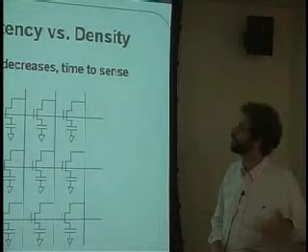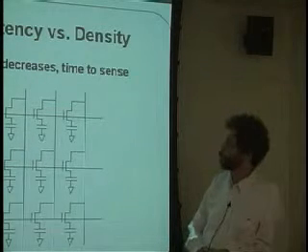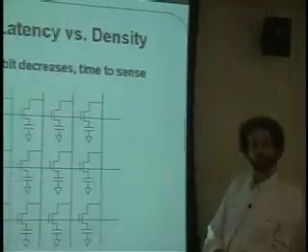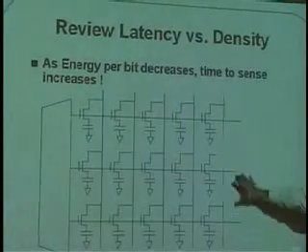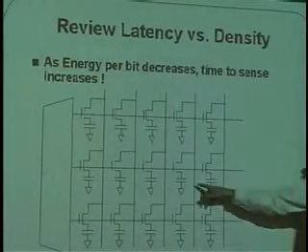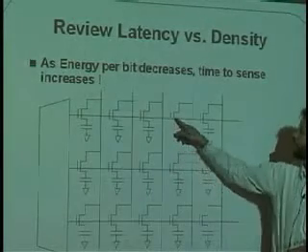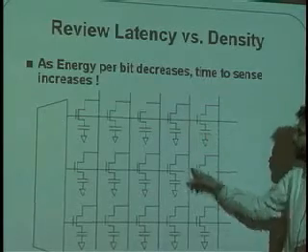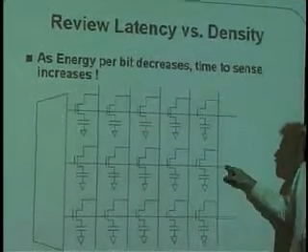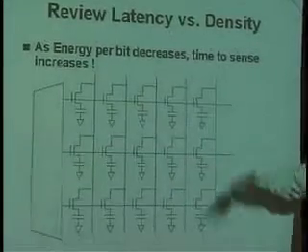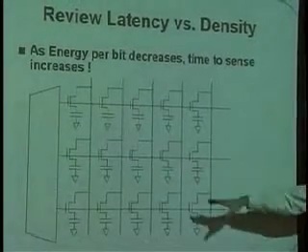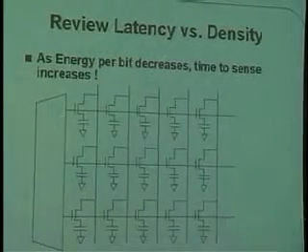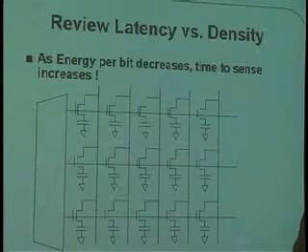There are some physical reasons for the trade-off, and we hinted at those at the beginning of the first lecture of the course. The first has to do with something that you understand very well now. This is a picture, if you recall, of a DRAM. Each one of the capacitors here is storing a little bit of charge, and these are the transistors used to connect that capacitor to one of these sense lines that goes over here. And this is a row select line that's choosing the whole row. But if I were to try to shrink this chip down and make these capacitors very, very small, as I shrink them and shrink them, what happens? The amount of energy that they store goes down.